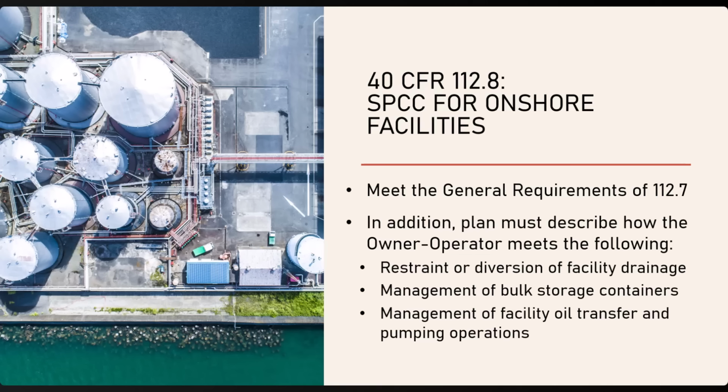The SPCC rule specifies requirements for buried piping designed to prevent leaks from deterioration. It also specifies inspection requirements for piping and transfer areas. All of these 112.7 and 112.8 requirements might also be subject to state or local requirements. If applicable, these should also be considered for inclusion in the SPCC plan.